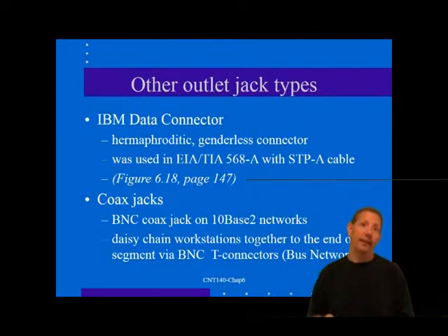There are 2 methods to connect the cable sections to the rear of the faceplate. One method connects bulkhead-mounted female connectors directly to each cable end. Each connector is inserted through a D-keyed hole in the faceplate and secured with a thin washer and nut. The alternative method places 2 bulkhead mount barrel connector adapters in the holes of the faceplate. The coax cable ends in the wall are terminated with male BNC connectors, which are then connected to the backside of the bulkhead adapters from the front. The faceplates look the same regardless of the method you use to connect the ends.